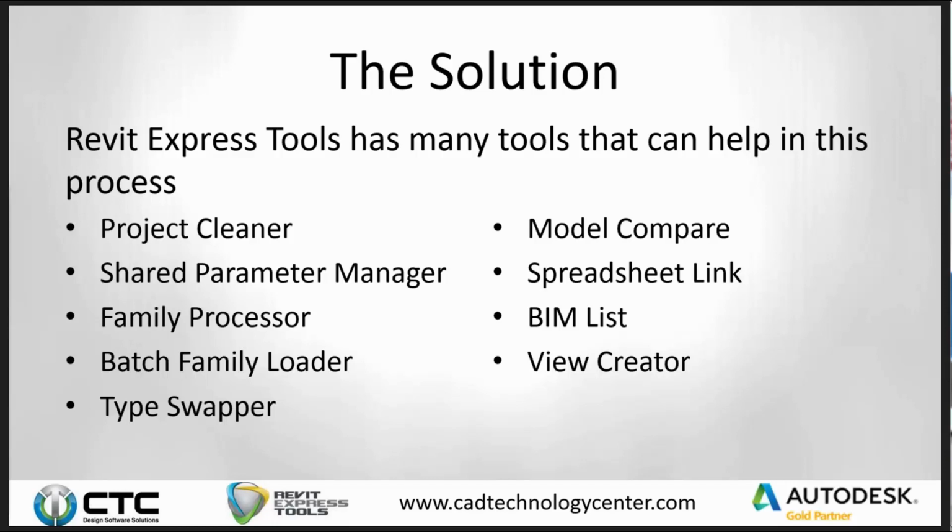You guys have probably seen me a lot of times use Spreadsheet Link to correct information and to batch use Excel formulas to update some information. We'll be using that throughout this presentation as well in different ways to correct some data. Of course, I'm a big fan of BIM lists because that helps me keep my standards in alignment as I'm going, but it also helps me bring standards back into alignment in some cases. And we'll take a look at another alternative way of leveraging BIM lists to do that.